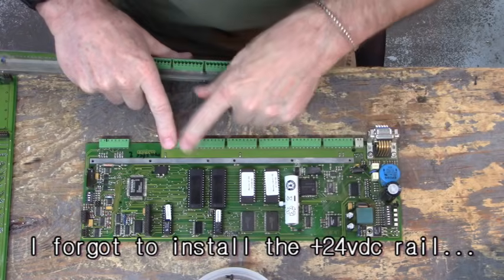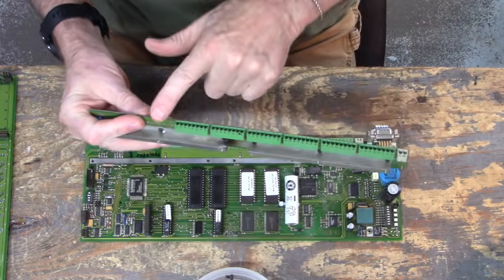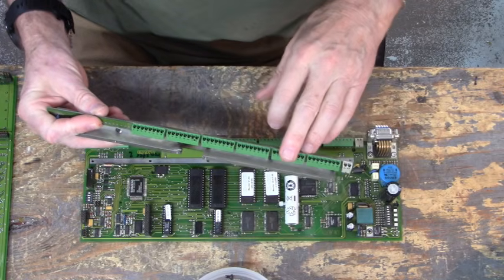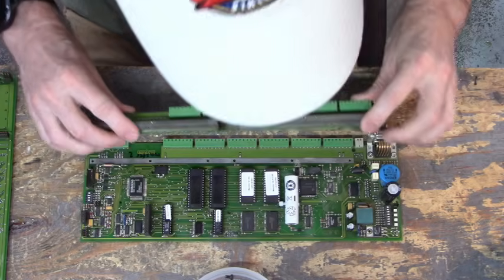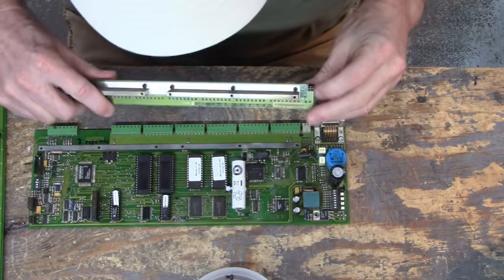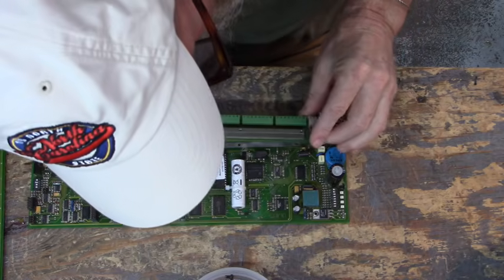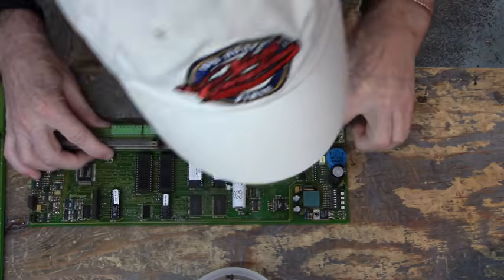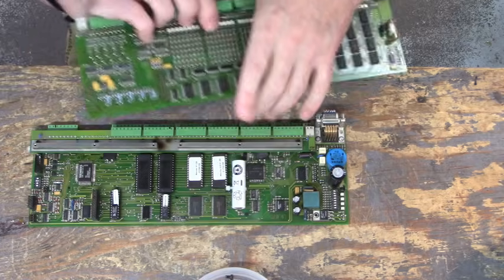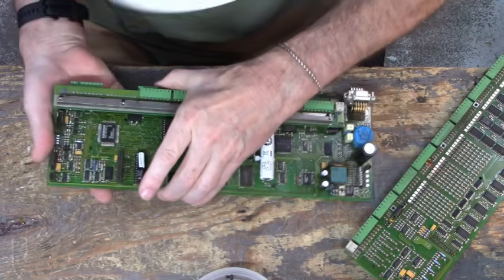So all of these connectors down here are 24 volt ground, and all of these connectors right here are 24 volt in. The ground and the 24 volt in plus 24 volt is for the I/O on the top board. And there's a stake connector over here that connects this 24 volt to the 24 volt power supply. So you've got to get this stake connector in right here. Now, okay, let's do this 10 more times, trying to get those stake connectors lined up.